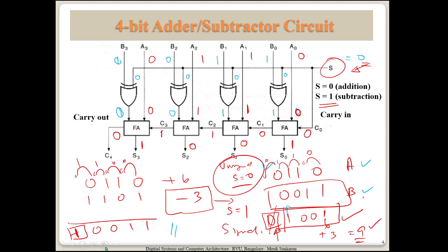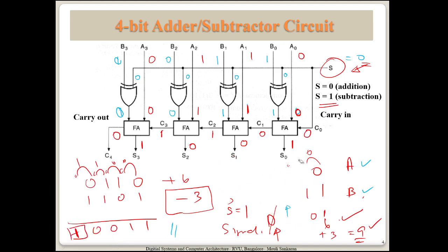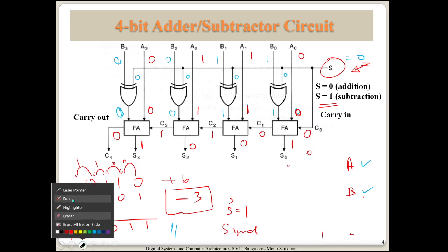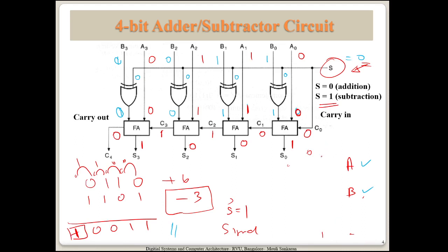Now what if I am doing a signed arithmetic? So let me erase this. Now I am performing a signed arithmetic. Okay, in this circuit I am using it this way and then performing it. So let us do it now. A is plus 6, which is given as 0 1 1 0, and this we are feeding. What we are doing is plus 3, and we are feeding the same numbers, plus 3, but we are going to be doing a minus arithmetic, right?